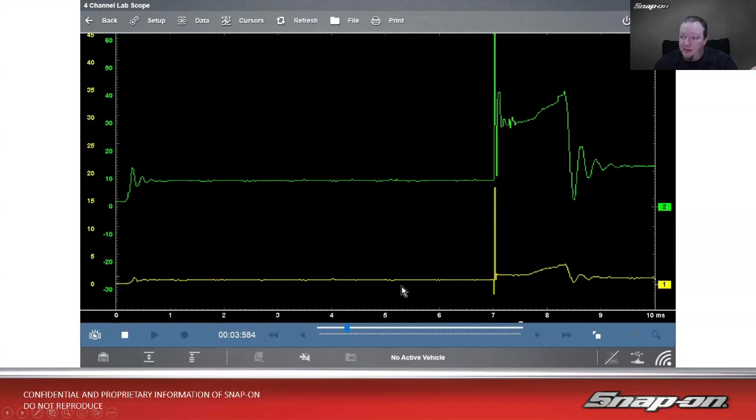So we see this is the primary, comes in, we got our firing line right there, and we'll talk about all this in a minute. Firing line, spark line, coil oscillations after it's done firing. On the secondary side, you see I get a lot more detail. I got more oscillations on that side. I get a firing line with a little more detail, spark line with a lot more detail, and then this with a lot more detail.